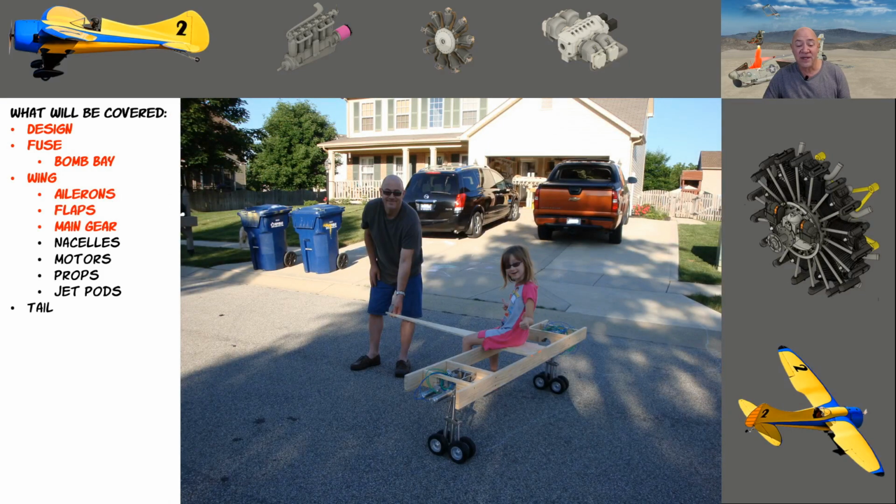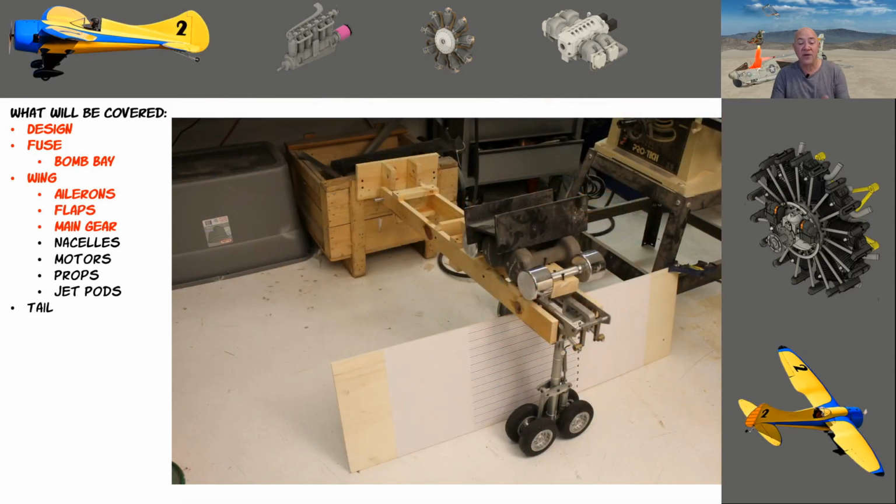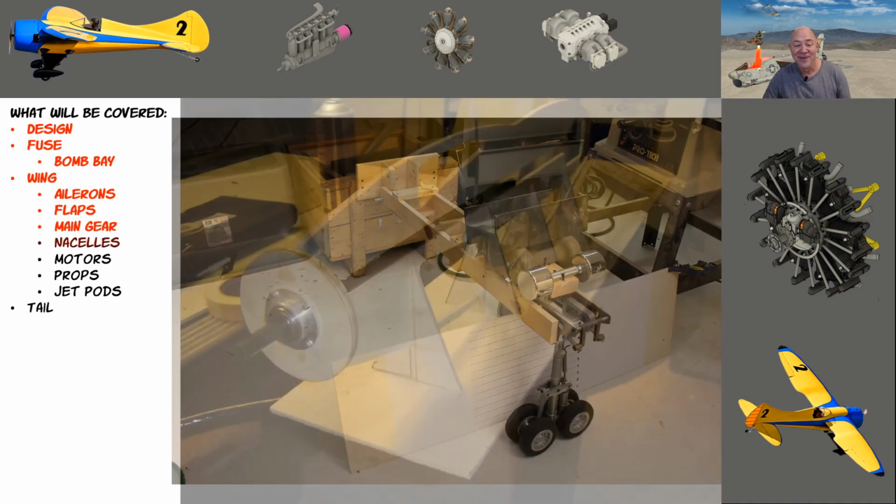And here's a little bit of testing of the landing gear I talked about. And here was what I call the brute testing, where I just piled on about 70 pounds of weight and would drop 12 inches, which was giving it some enormous amount of G-load that the airplane couldn't even survive, and the wheels were fine. And that's how I did it.